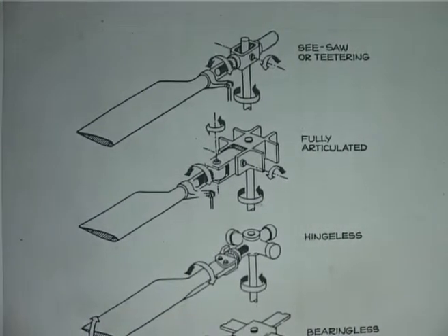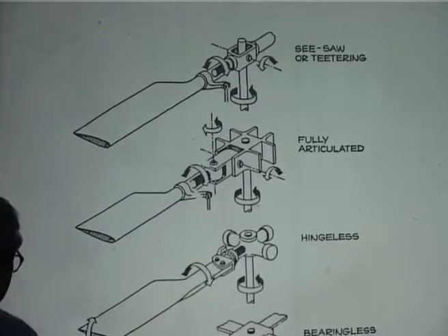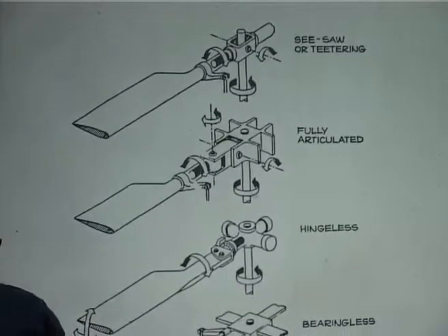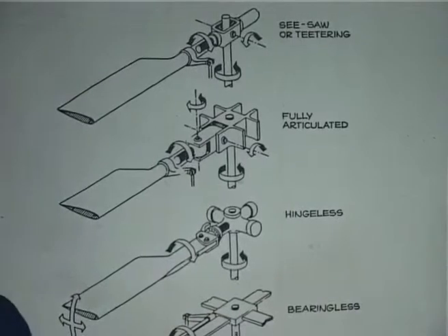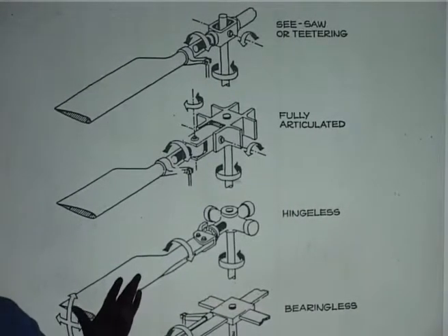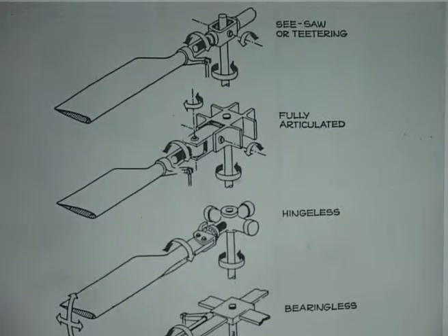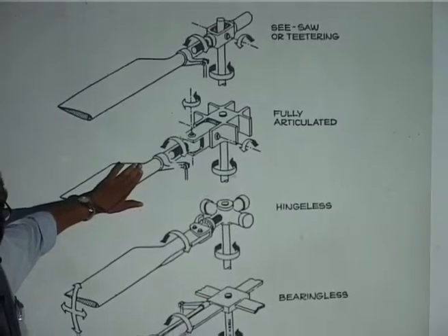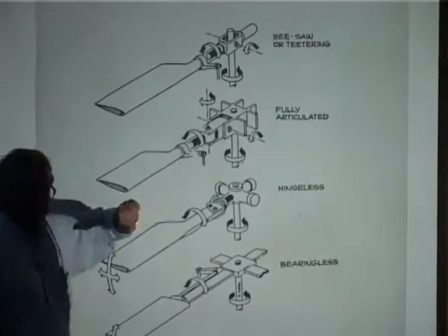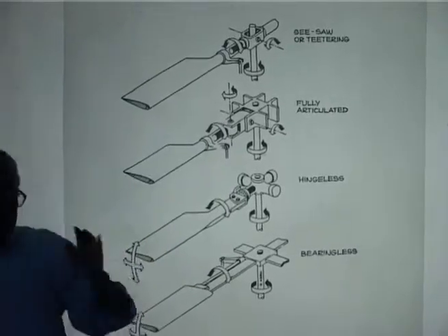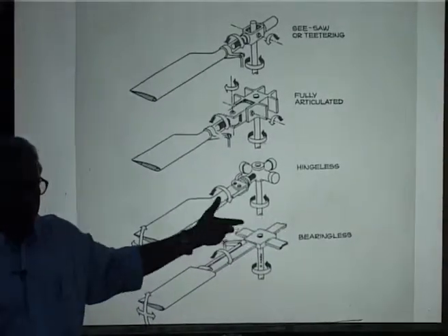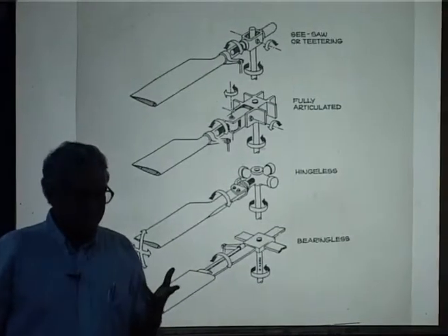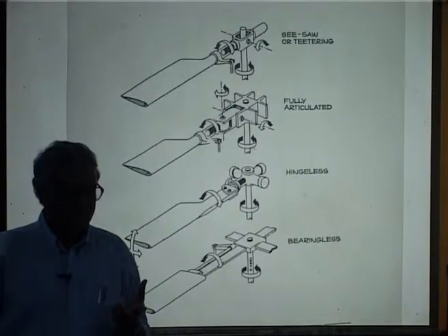All the helicopters were built like this. Even the attack helicopters, the Russian helicopters, everything till the 80s, though of course some slight change will be there, are like this. But now, you know that when you have a physical hinge, the blade is going up and down, what will happen? You have wear and tear problems. Maintenance, number of parts, everything is high.